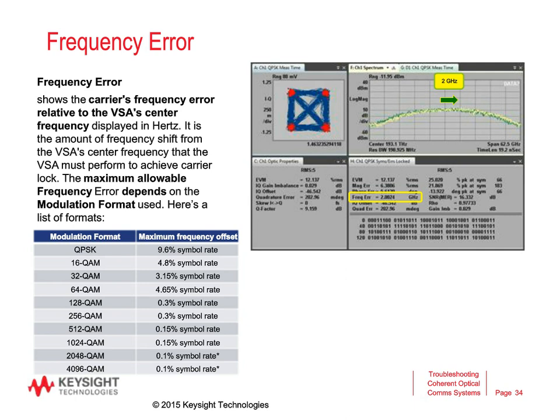The QPSK, for instance, is almost 10% of the symbol rate that we can track. With QAM 256, we are already down to like 0.3% of the symbol rate. So the higher the modulation order goes, the more precise I have to be in terms of the matching between transmit and receive frequency.